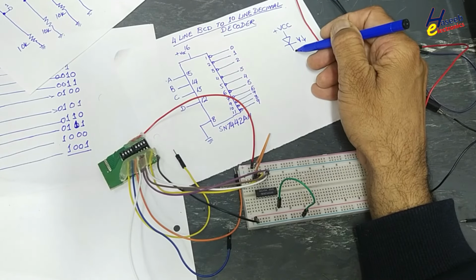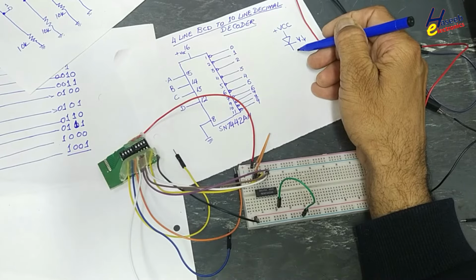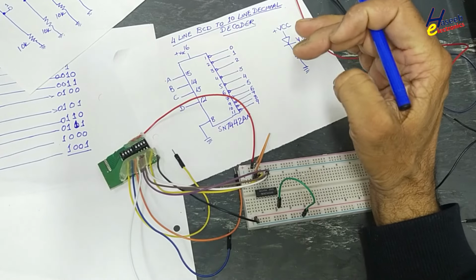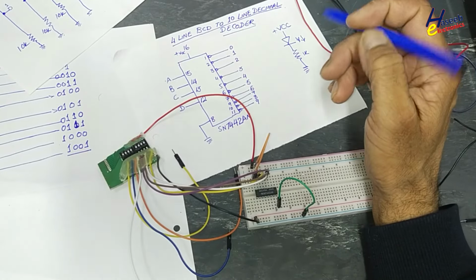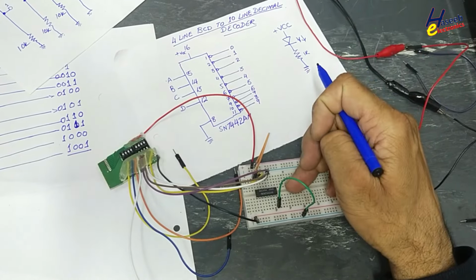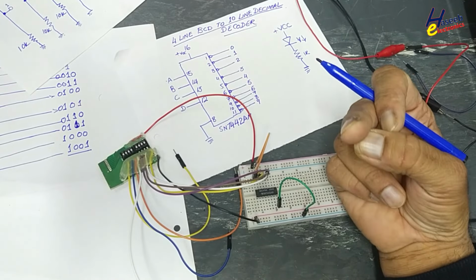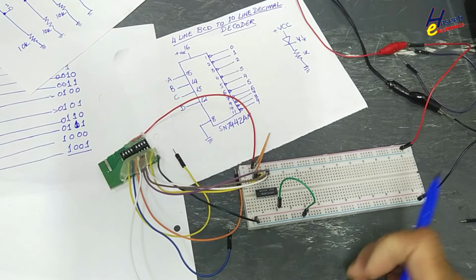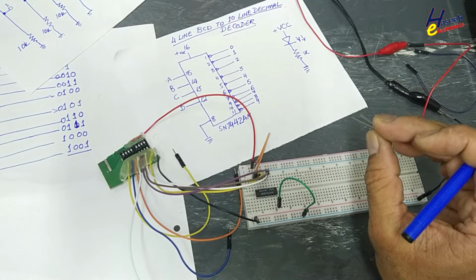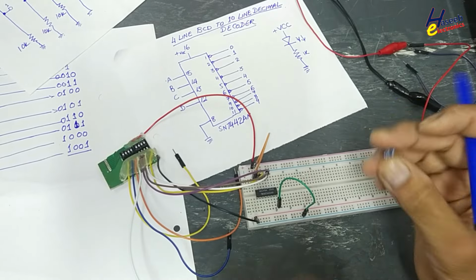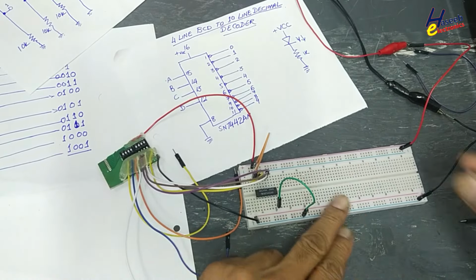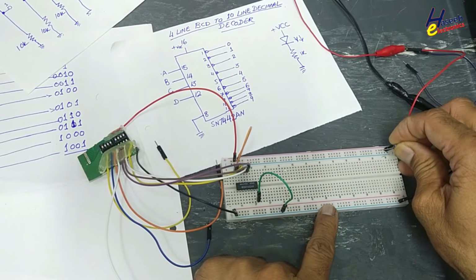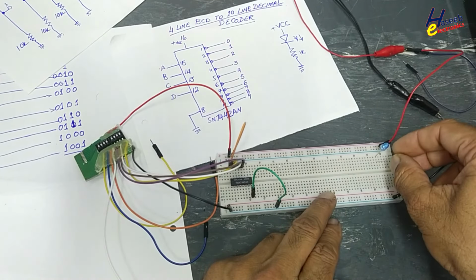You can use a 330 ohm resistor, you can use 560, but I am using a 1K resistor to minimize power dissipation, because a maximum of 16 milliampere can be taken from one channel. With a 1K resistor the LED will provide dim light, but that is enough to see the result. Anode, long lead, to the positive side. 1K resistor to the cathode.